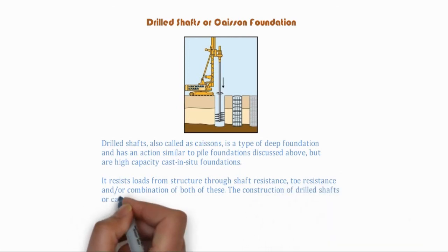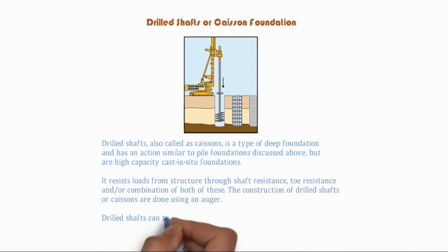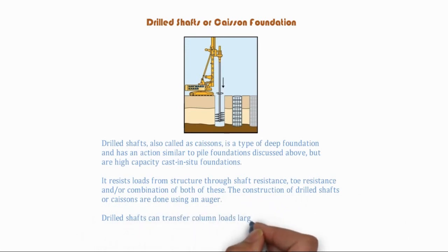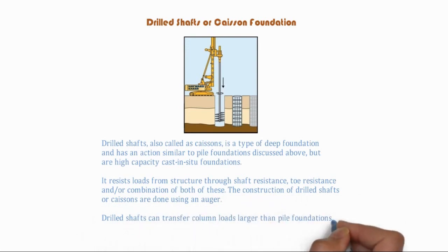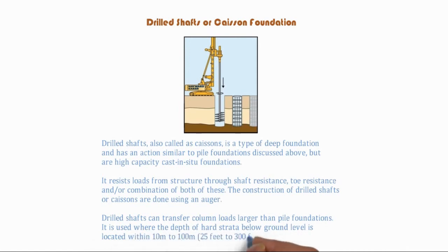Drilled shafts, or caisson foundation, is not suitable when deep deposits of soft clays and loose water-bearing granular soils exist. It is also not suitable for soils where caving formations are difficult to stabilize, soils made up of boulders, artesian aquifer exists,